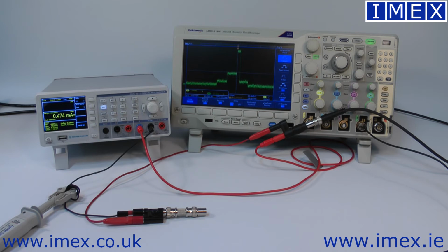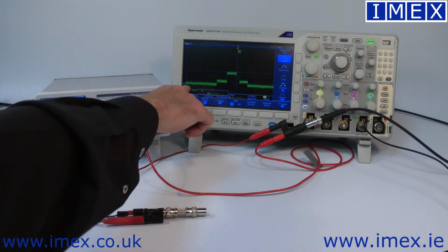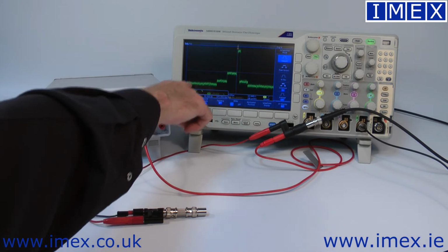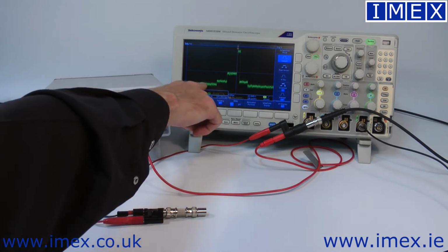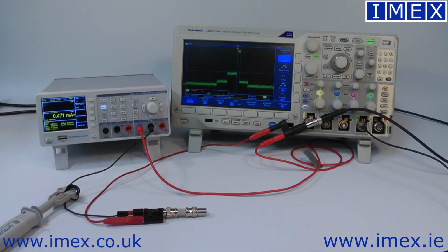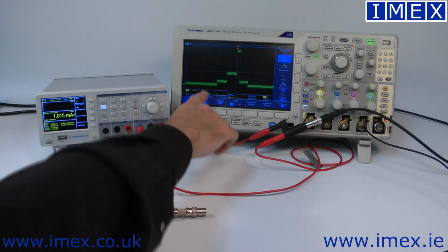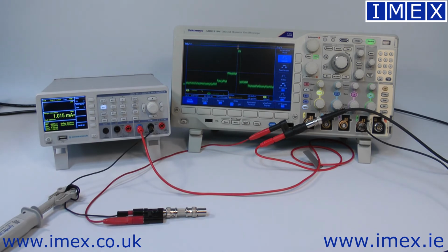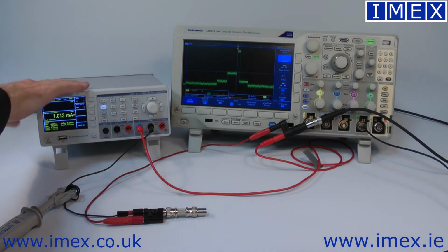Yeah, it's usable. We do suffer a little from the offset of the probe, where you couldn't really trust it to make an accurate measure of this sleep current, but you could use a normal DMM to measure that and get your current profile off that. Not ideal, but it's doing a better job than our DMM did.